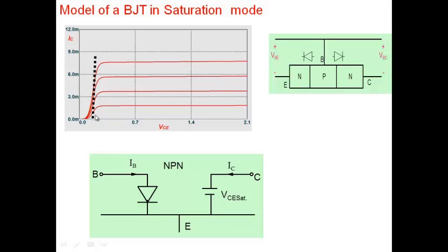And the straight line, this voltage is what we call the saturation voltage here, VCE sat. Whatever is the collector-emitter voltage in the saturation region. So what we are doing is approximating all these characteristics, this falling characteristic, by a straight line. And when you do that, a straight line means the voltage is constant. Straight line means the collector-emitter voltage is a constant, and that constant part is what we put here. So that's a very simple model for the transistor in the saturation region.